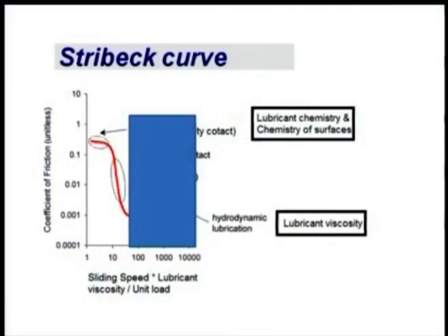If I see the other side, the left hand side of this line, if I do not consider the right hand side, I consider only the left hand side. Now, in this case heat generation is high, temperature is high, and because of that viscosity is decreasing. Decrease in the viscosity will reduce the bearing number. If the bearing number is decreased, this is going to further increase the coefficient of friction. Increase in the coefficient of friction will increase heat generation. Increase in heat generation will increase temperature, that will reduce viscosity. So, this is a compounded effect.